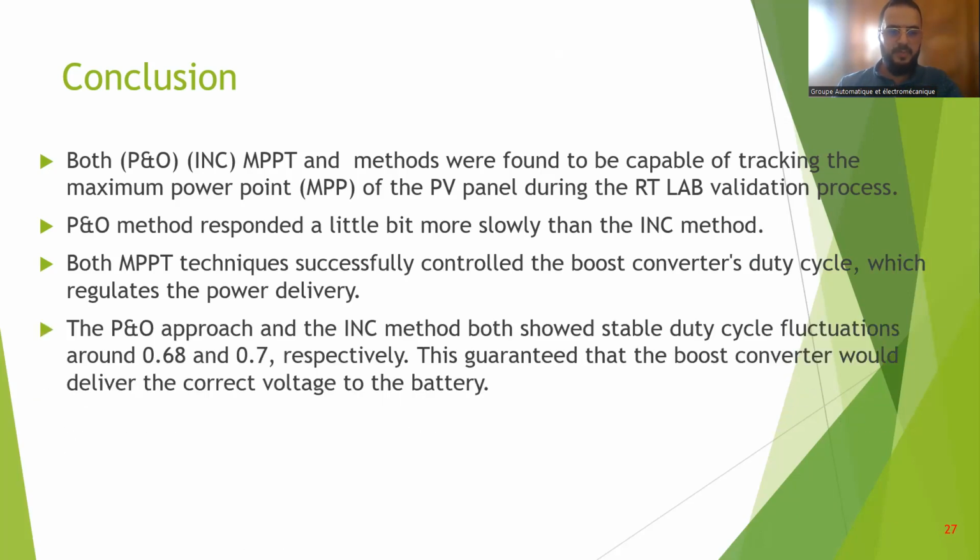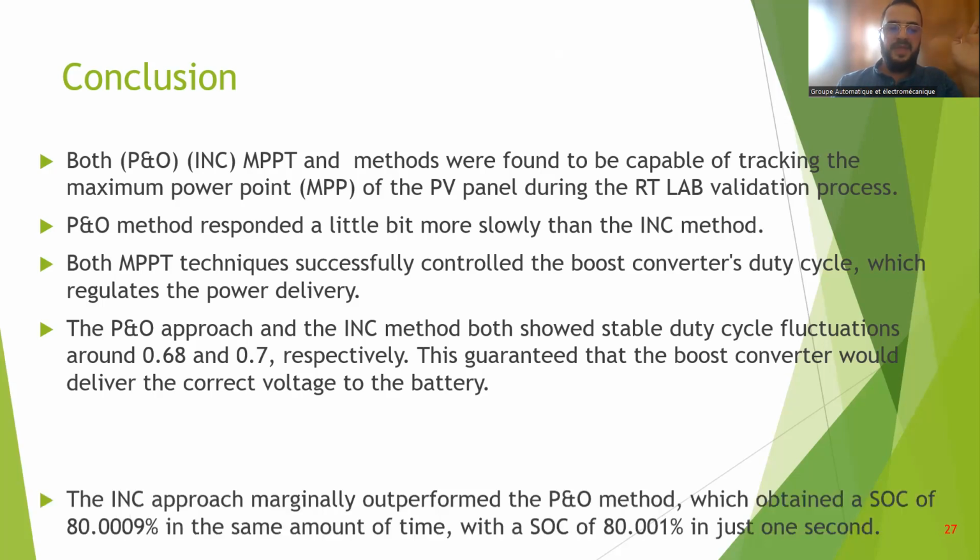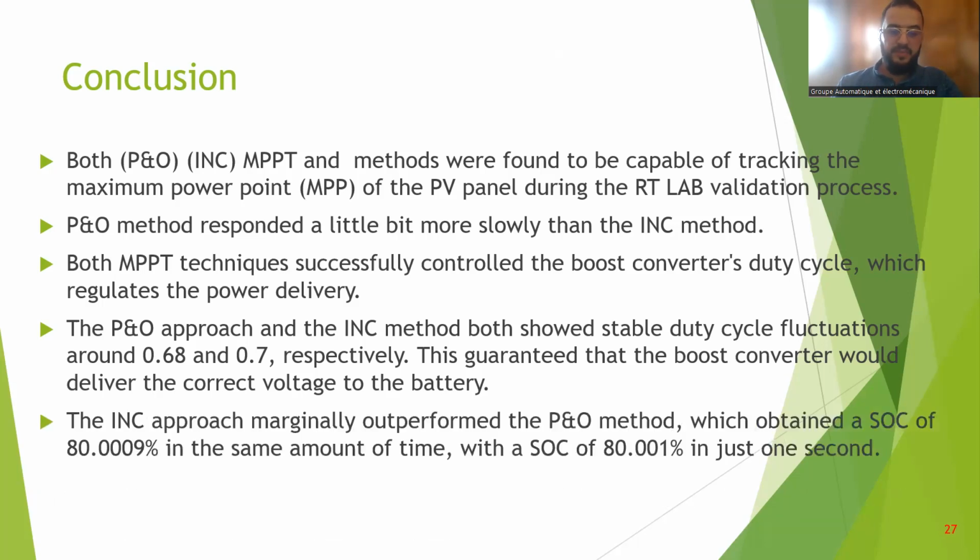the incremental approach shows that we have a stable duty cycle fluctuation that guarantees that the boost chopper would deliver a correct voltage to the battery. The incremental method approach marginally outperforms the perturb and observe method if we look at the state of charge. Thank you.